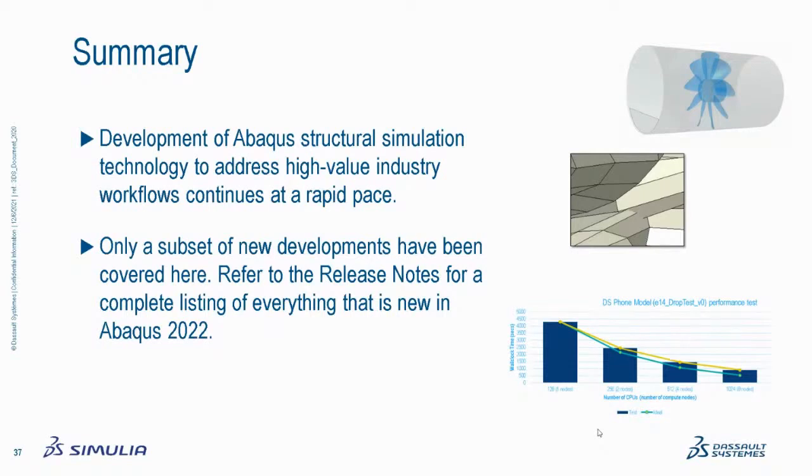Just for those maybe that aren't familiar with the question here, on Intel processors we have this thing called hyper-threading. That essentially allows software to see a single core as two cores. You don't use that with Abaqus. It doesn't really make any sense. So you definitely want to have that disabled, and cores or CPUs on the command line means a physical core, not a logical or hyperthread.